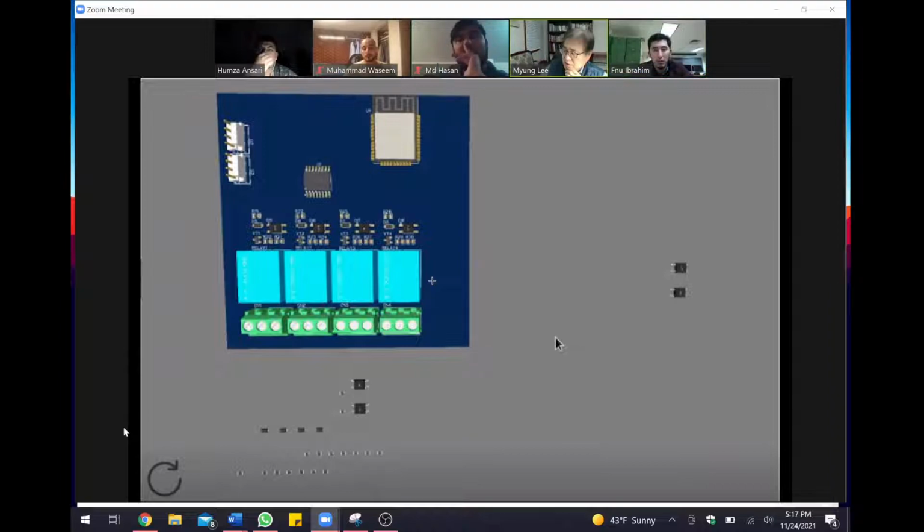I think what I'm saying is that maybe you may want to separate these 4 relays and spread them out. I understood your point. If I put all these relays in different corners, for example... But it's not safe, because under this is the power, and the power is going to damage other components.